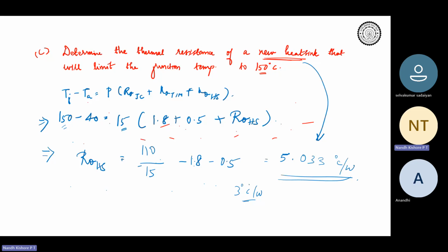And with water cooling, which people go for if you're going for very high kilowatt, very high power, then you will see that there is a large heat dissipation. Your heat sink requirement will be something like 0.1 degree per watt or even lesser. So to achieve that, people go for water cooling. They will circulate water. Imagine something like what happens in your refrigerator. You would have studied the operation of a refrigerator. It basically takes away the heat by circulating a coolant, right? The same principle will be used over here also.